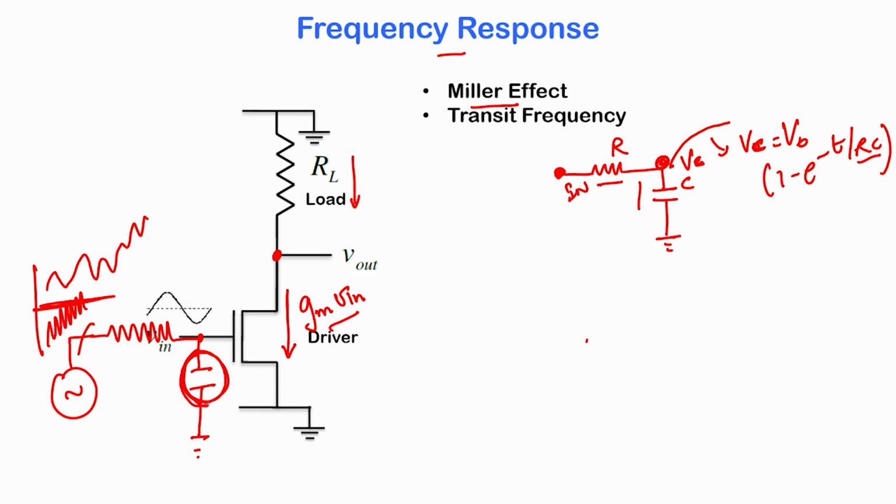The way you define this capacitance is to see what are the elements the transistor is driving. So, on the face of it, this capacitance is basically your gate to source capacitance of the MOSFET. There is a channel here and there is a gate to source capacitance in the MOSFET. Okay, so that is not the problem, that capacitance is there in any case. Now the problem arises because of the gate drain overlap.